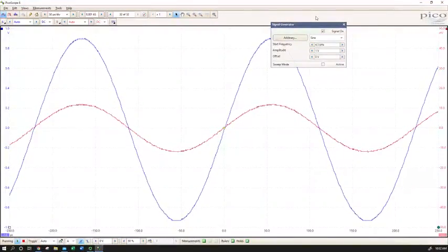We can put that together with our 4.7 nanofarad capacitor, back ourselves through our F resonance formula, and get an inductance of about 1/4 of a Henry, between 0.2 and 0.25. In my earlier measurement, I measured about 5,000 hertz for F resonance, and that would have given me an inductance of 0.2156 Henrys, 0.22 Henrys. I wouldn't give myself more than 2 decimal places given the uncertainty of this measurement.